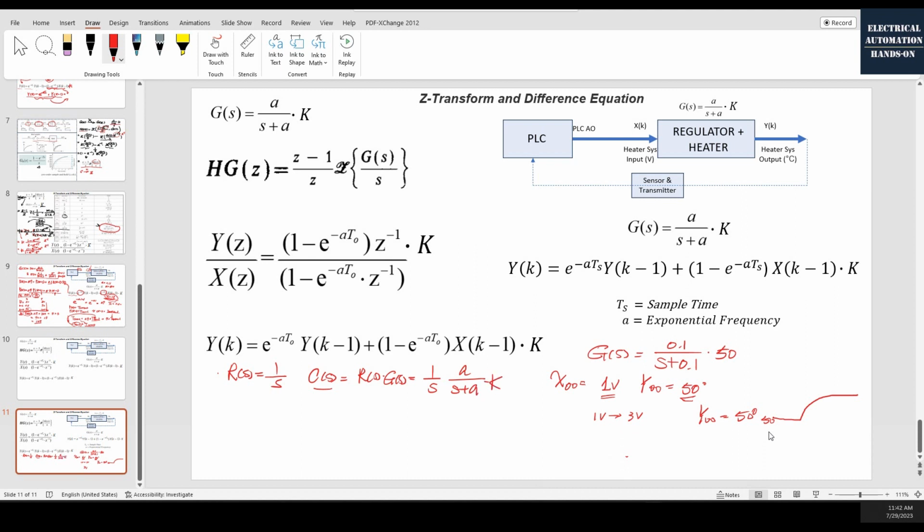And then to calculate a step response, the settling value, we'll use the limits. This is the limit when the time goes to infinity, which means s approaches 0. That came from this equation, s times C(s).